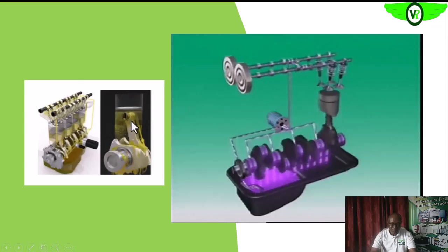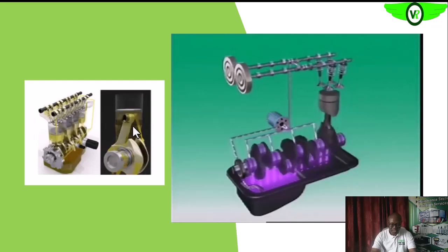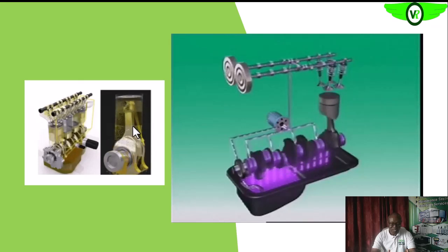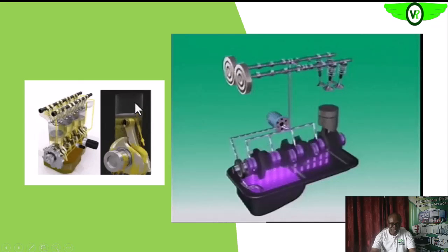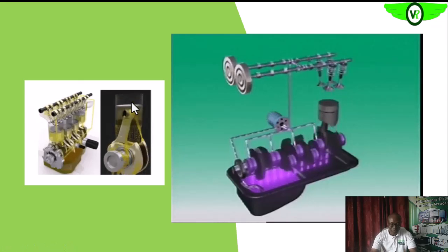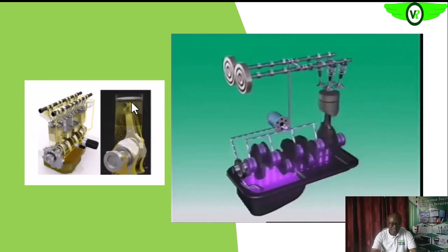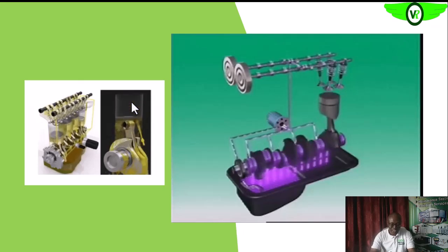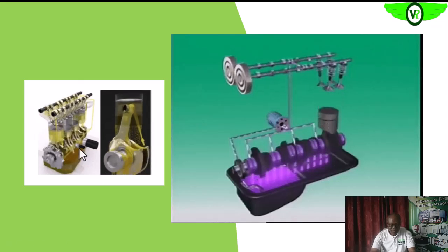Okay, so on the piston, you know, we have three sets of rings. We have the wear rings, we have the oil rings, and we have the compression ring. So the compression ring basically is to assist us so that during the compression cycle, compression is not lost from the cylinder, while the oil ring is like a scraper ring that helps to scrape the oil down. Okay, then we have the wear rings that we sacrifice for the piston and the cylinder or sleeve in the cylinder itself. So that means preferentially the wear rings will wear compared to the sleeve or the piston itself.